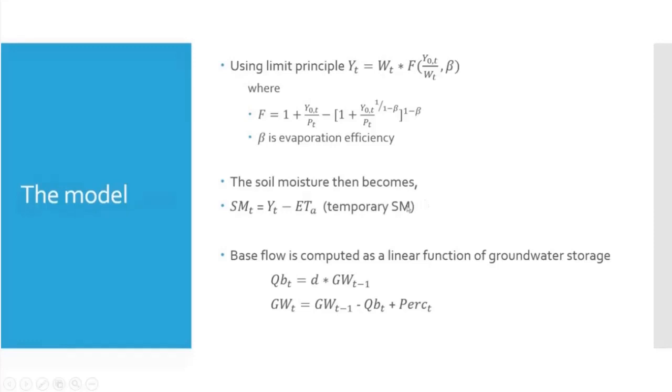And the base flow is computed simply as a linear function of groundwater storage, which is some parameter multiplied by the groundwater storage. And the groundwater storage will be updated by the previous groundwater minus the base flow plus the recharge of the percolation.